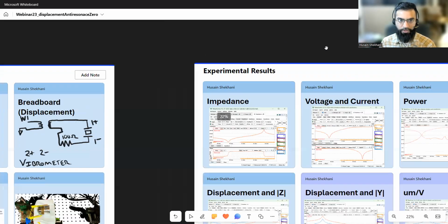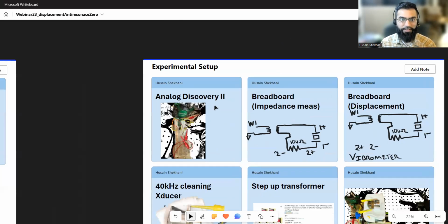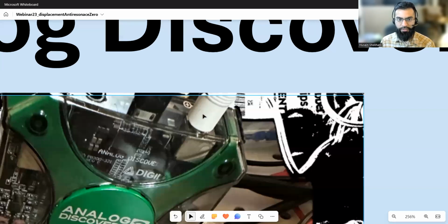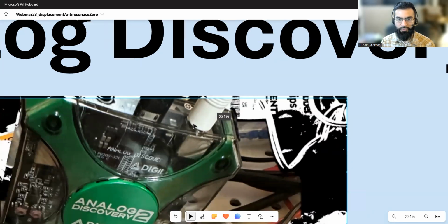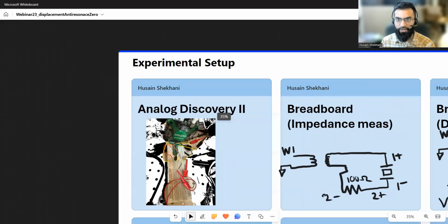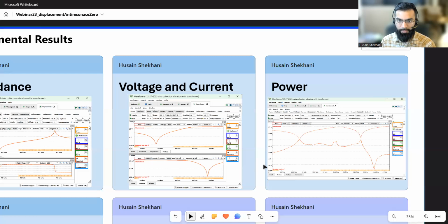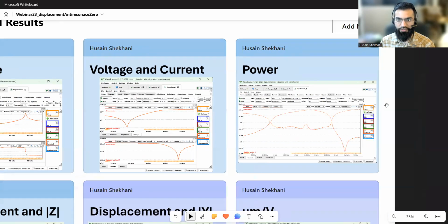I also want to mention one thing while we're at it, is that I did end up having to use a 5 volts DC supply additionally to the USB power source from the computer. Putting a 5 volts supply on there allows the waveform generator to actually work in the conditions that I asked it to work. Because although we'll be drawing like milliwatts or even microwatts over our transducer, the Analog Discovery is actually perhaps putting out hundreds or at least like 100 milliwatts probably of power just to drive that empty side of the transformer, which is almost like short-circuited in a way.